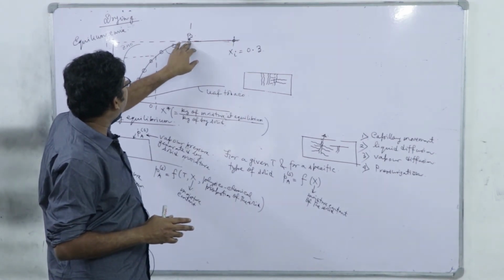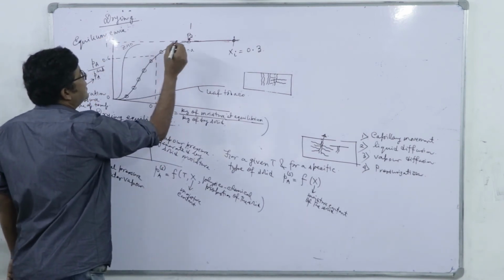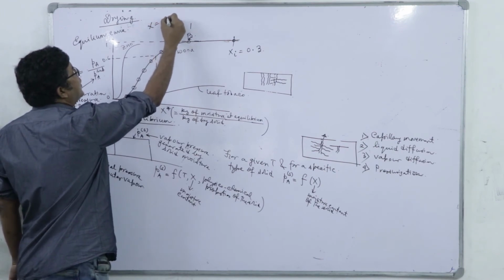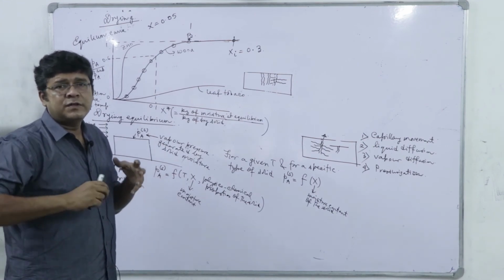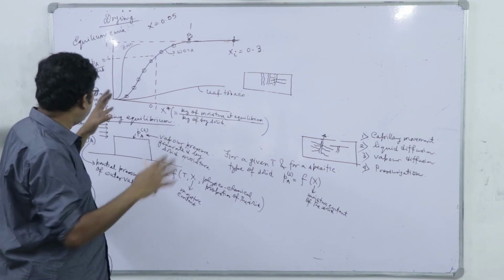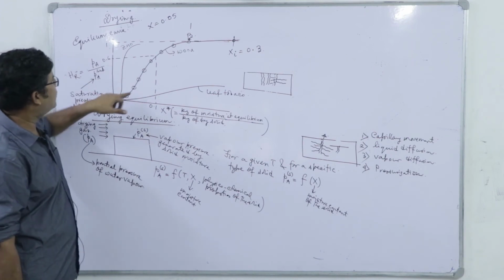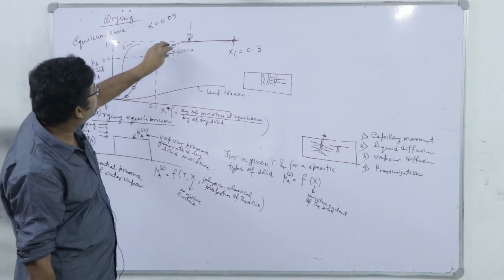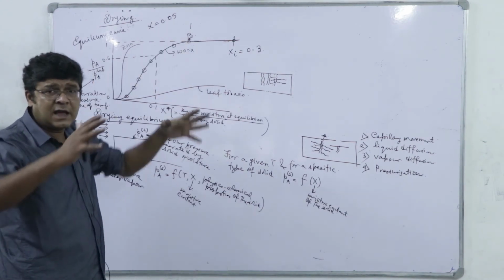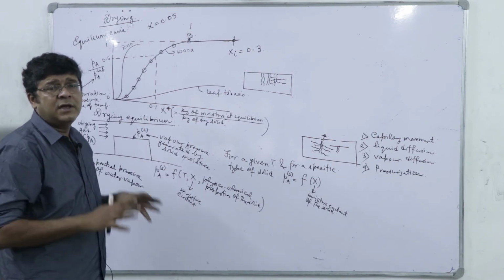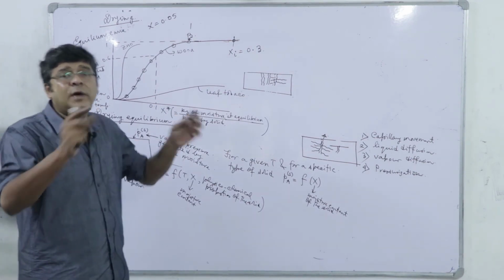if we think in the reverse direction, wood has a moisture content, say it is 0.05, right, somewhere here, and we expose it to a drying medium which has a relative saturation equal to 1. What will happen? It will acquire moisture upon adsorption and ultimately attain equilibrium at this point B. So, all the capillaries of the wood are filled to their capacity of holding water, right, but there is no external film.